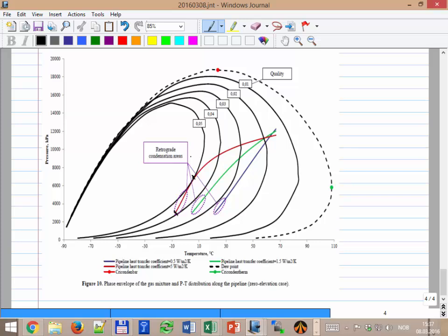And you have to run sensitivity on the different insulations and see what is the difference in the inlet pressure. You see that the pressure is different, so why is that? Why do you think the inlet pressure is different for the different insulations? Okay, remember that delta P has two components. I have the gravitational plus the frictional loss.